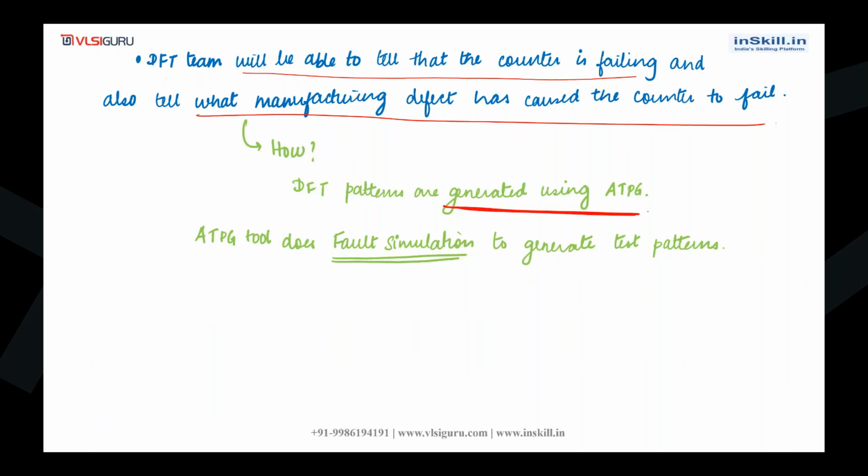The ATPG tool does fault simulation to generate the test patterns. And what is the fault simulation technique? We will understand it when we do our regular course. When we do the course, you will be able to understand what fault simulation technique is. So DFT will be able to tell that the counter is failing, and also tell what manufacturing defect has caused the counter to fail.